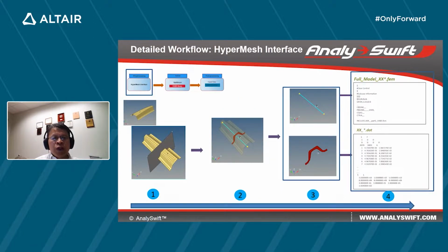For example, for a composite beam with a channel cross section, what we can do is cut multiple cross sections along this channel, and of course, the channel could have different cross sections. Then we split the problem into the beam element, which is whatever existing beam elements in OptiStruct, and the cross section with no mesh.